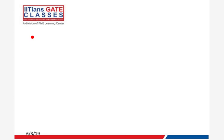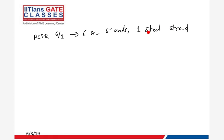For an ACSR 6 by 1, right? It means 6 aluminum strands and 1 steel strand, right? So that means 1 layer of steel and 1 layer of aluminum.